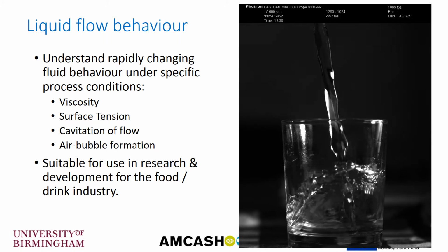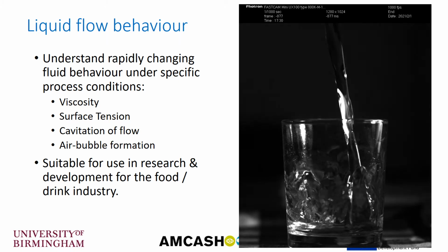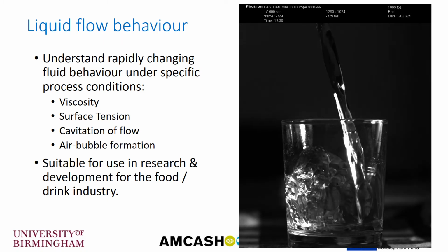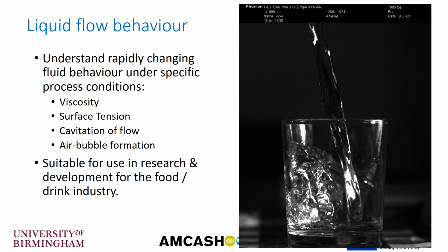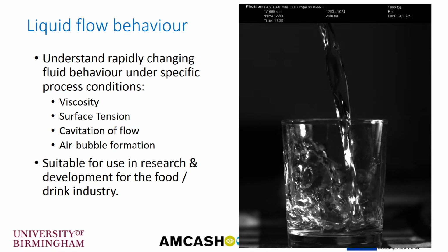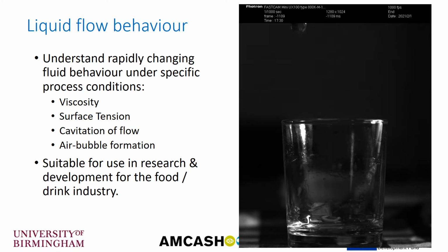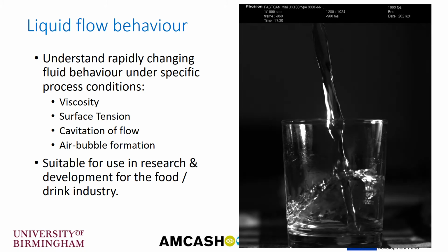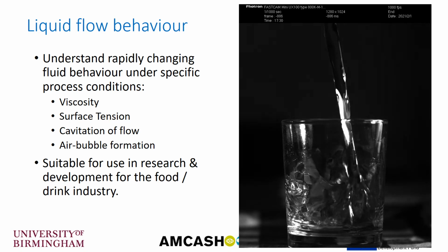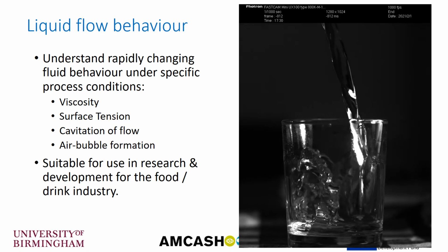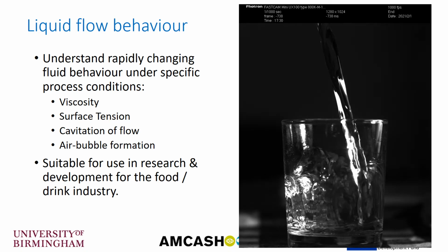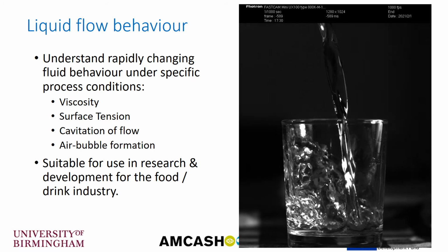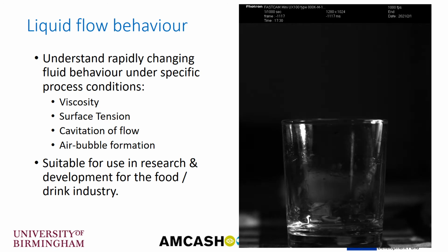We can use the results to measure what the viscosity of the fluid is, and we can imagine doing an experiment at two different temperatures and seeing how the viscosity changes with temperature. We can try and use the video to analyse to see what the surface tension of the fluid is. We can look at cavitation of flow, so when do we lose that steady state pouring of the water into the glass. And within the water that's settling in the glass, we can look at air bubble formation. So this kind of use of the camera is suitable for maybe research and development within the food and drink industry.